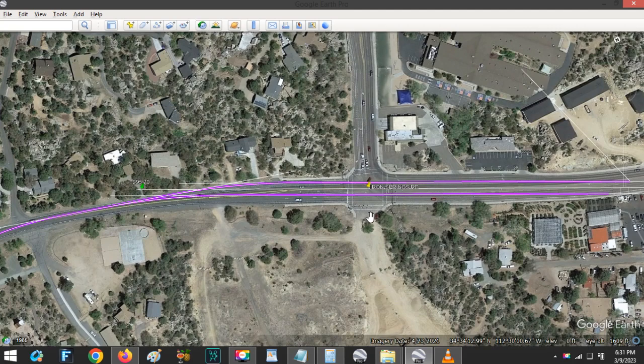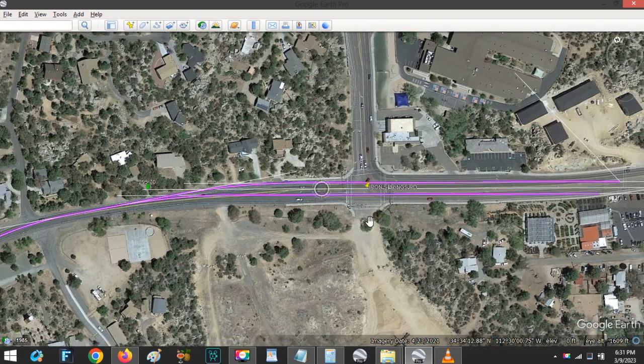And you can see the dip in the station. The station's about 650 feet long, and the entire dip and vertical curve is accomplished almost entirely within the station, I would say. And if you didn't know it beforehand, you would never notice it. So a more broadened out vertical curve in the opposite direction here probably wouldn't be of concern to anybody.